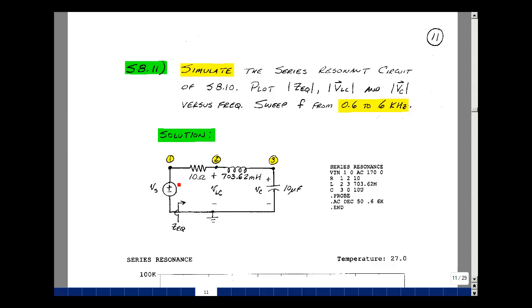Okay, let's take our circuit with our values. Label the nodes. I'll call this 1, 2, 3, and ground. And let's describe our circuit. Need a title, need a .end. Our voltage source is between nodes 1 and 0, plus sign, minus sign. Has a value of 170 at angle 0 as a phasor, and you've got to say AC to indicate it's an AC analysis. If you leave the 0 off here for phase angle, it defaults to that value.